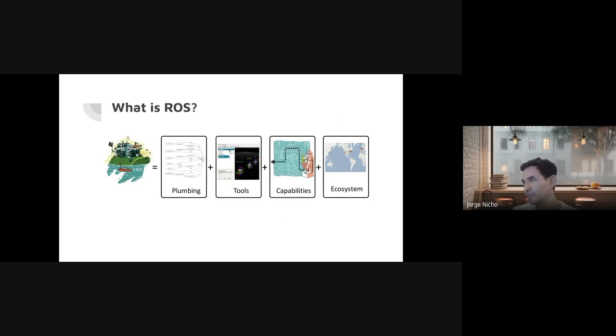And in addition to that, there's tooling. So there are already built-in tools for doing things that you would always do. One of those is the visualization tooling. So ROS has RViz, which is basically software that visualizes a lot of your data that comes through, right? So you can visualize images, you can visualize point clouds, you can visualize, like if you have a path that the robot's following, you can see that in RViz, and you can add additional things that are even interactive.